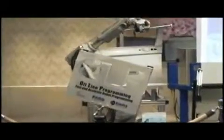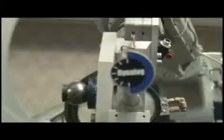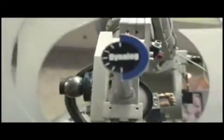This demo is showing the process using the laser tracker to take the calibration measurements, and then the Dynalog software takes those numbers, that data, and can improve the accuracy of the robot. The reason we improve the accuracy of the robot cell is to mainly eliminate a lot of the manual teaching that happens at the installation of the robot.